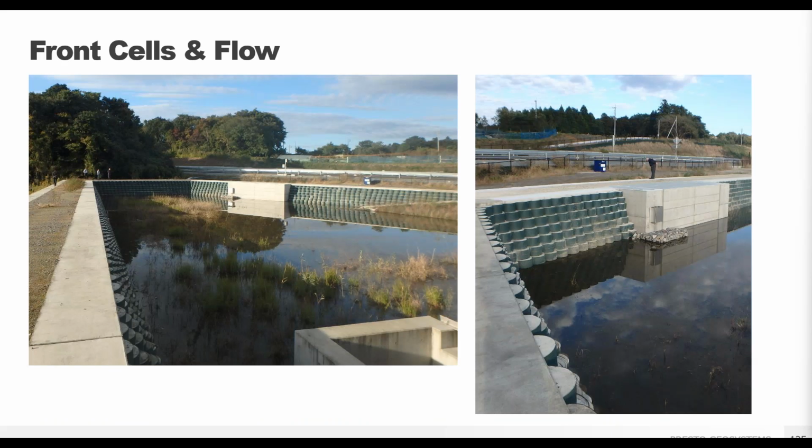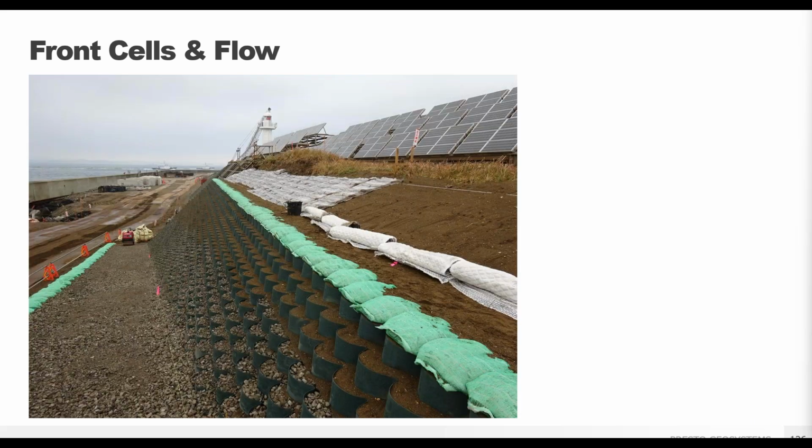We mentioned the drainable fill a few slides back. You may also consider grouting the front cells or filling them with concrete when any high flow conditions are expected, like this highway retention pond. Or a mix of medium, as you see in this project, with aggregate fascia along the pathway and topsoil for vegetation elsewhere.